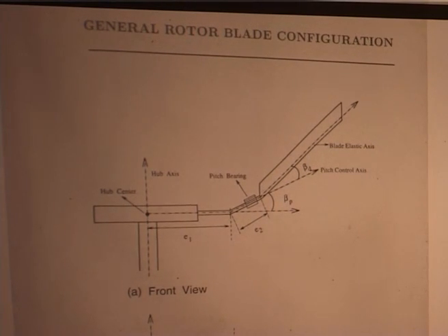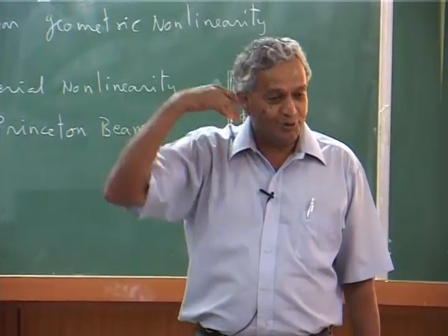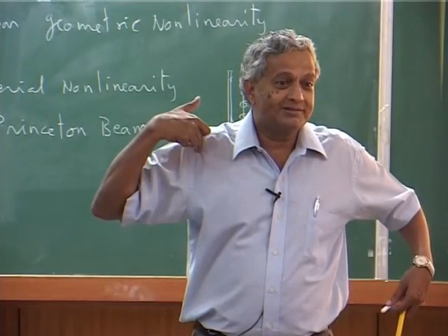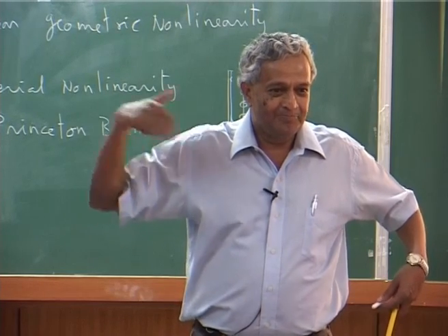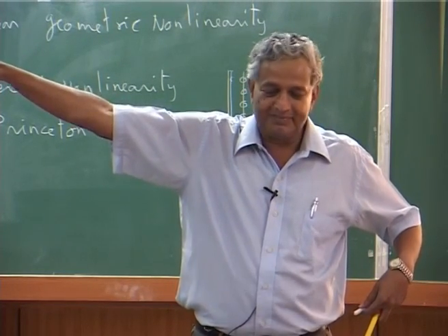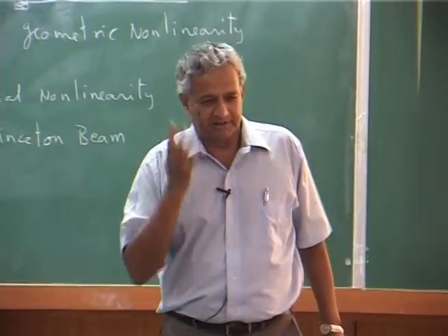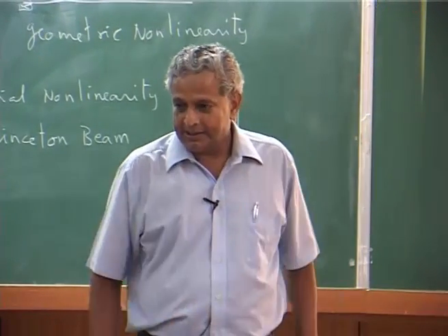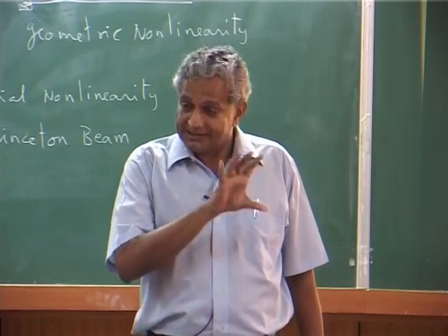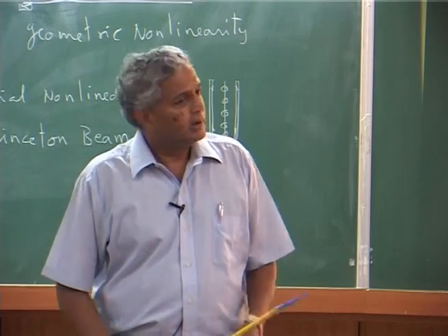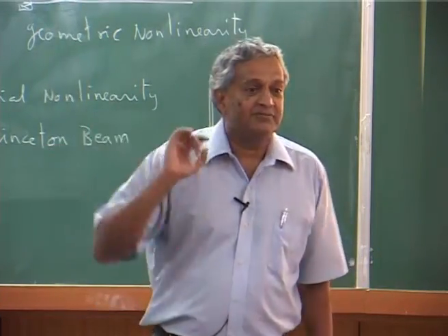See, what will happen is aerodynamic load tries to take it up, centrifugal load tries to bring it down, okay, and there is an equilibrium. Suppose your rotor blade is already kept at the equilibrium angle, there is no root stress. You follow what I am saying? That is why that is given, that Precone, relieving root moment in the blade. Otherwise, you have to make the root section a little thicker. But it will also transfer as a moment to the flap hinge. It will come, no, but elastic deformation.